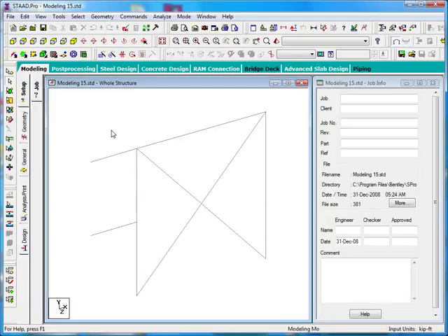The problems come in when an analysis needs to be performed, because while orphan nodes can be present during modeling, they should not be left in place during an analysis. They can cause errors. And so we have some tools that are available to identify, and then if we choose to, actually remove any orphan nodes that may exist in the model.